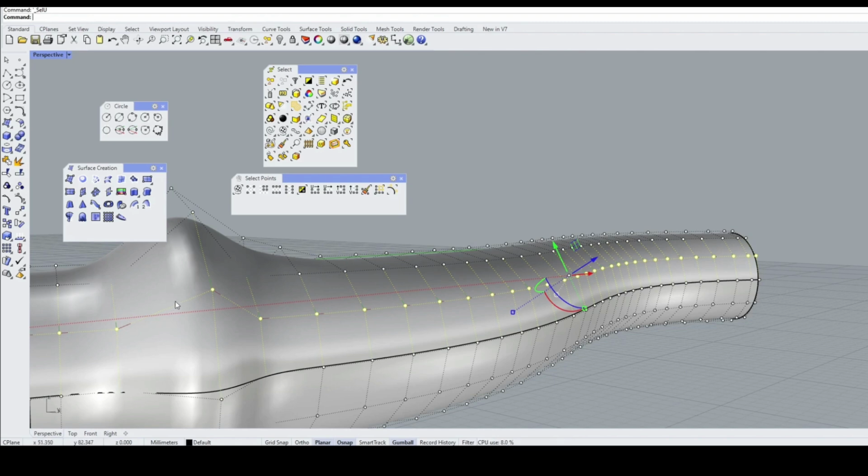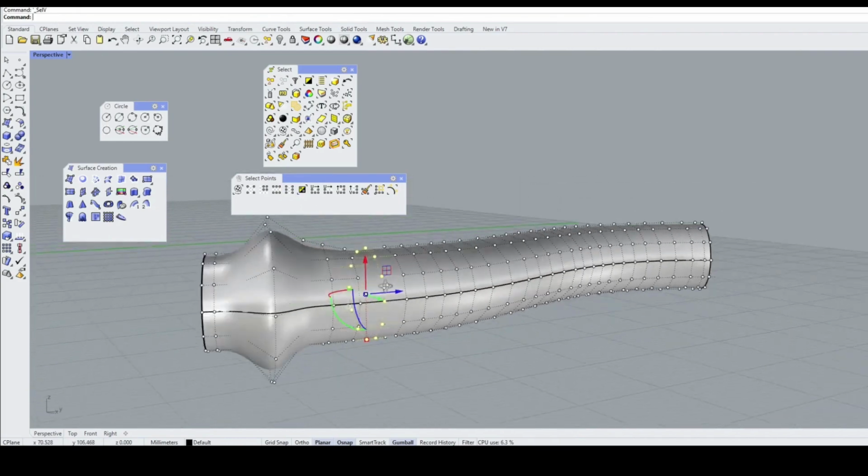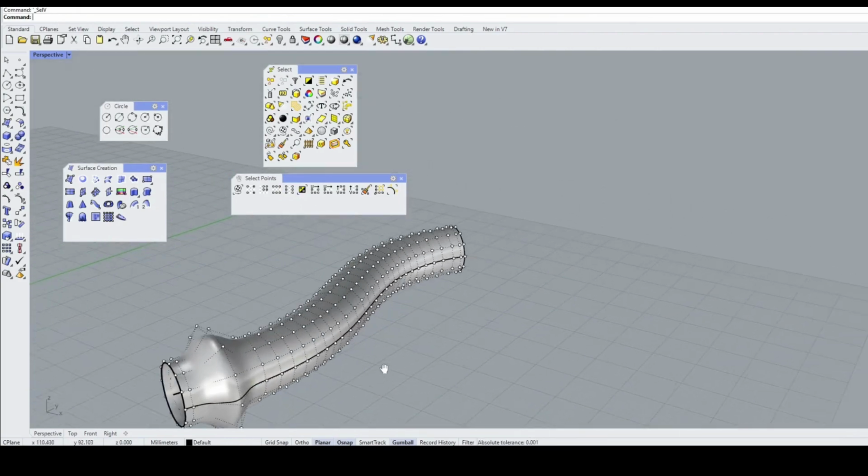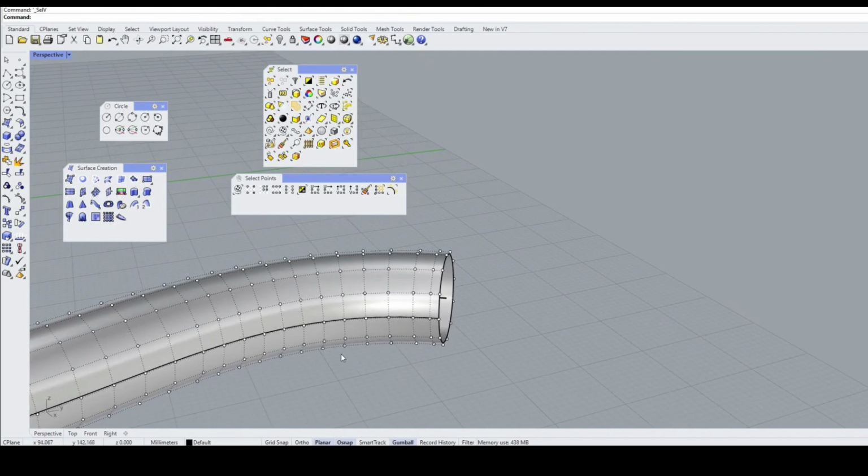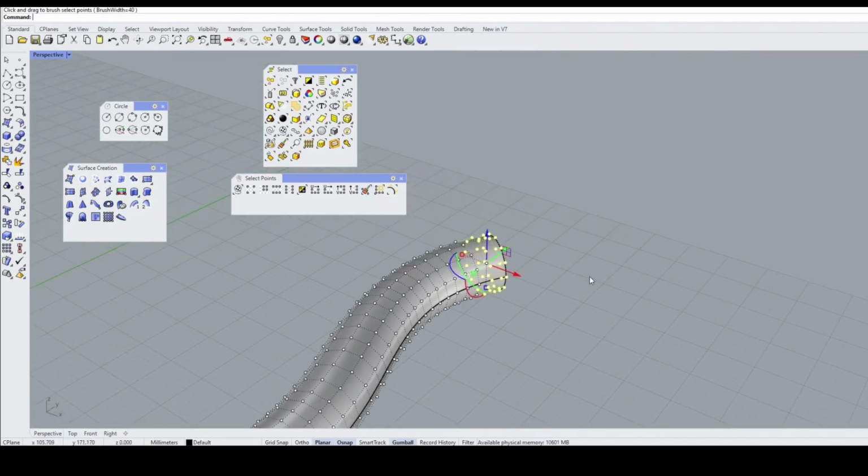Okay, in a similar fashion, if I want to select in the V direction, I can select any of the points that is on it, and then click Select V. Something like that. And maybe I'll talk about one more command, which is selecting points by brushing. If you were to click on this, you can select the points by simply brushing over that region there, something like that. Okay. Then with that, I come to the end of this demo.